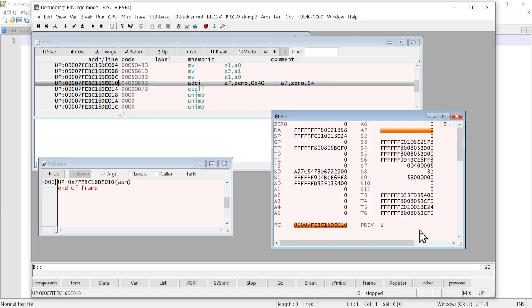This kind of information is not available when you look at any of the source code, but since TRACE32 is a hardware debugger, this shows you the current privilege mode. The current privilege mode is user mode. Please take a look at this. I will right click over this value and a small pop-up displays. User mode, HS mode. The HS mode is identical to the supervisor mode. And here is the machine mode. The M mode stands for machine mode.